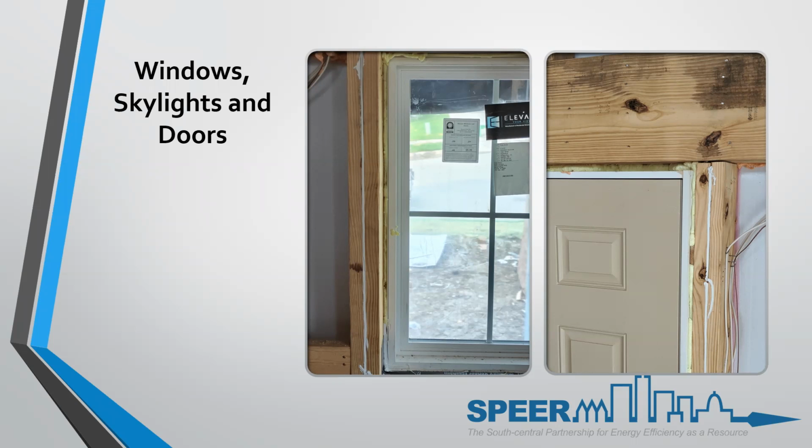So the doors that we see a lot now are big 9-foot or 10-foot doors. I'm up on the steps actually taking this photo to see the top of the door, but you've got to make sure the top of that's actually air sealed. A lot of times they'll do the sides and then they can't really reach the top, so they don't foam it, but you've got to be able to get up there and make sure that that is sealed. A lot of times the installers state that when they put the windows in, they're caulked around the frame as they hit the air barrier or framing members on the outside, but you can't always count on that. So that's why it's specifically called out in code that it must be air sealed in between these gaps.